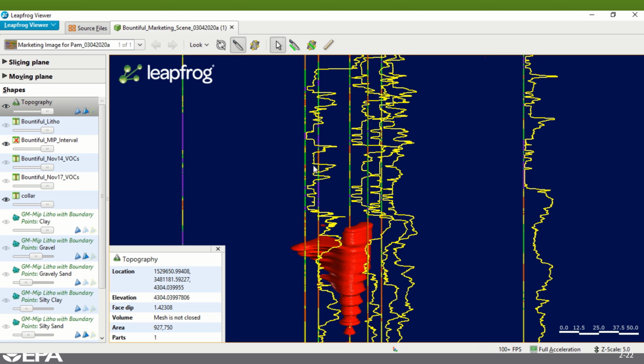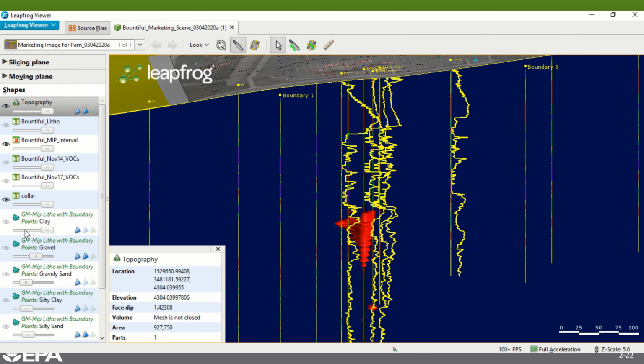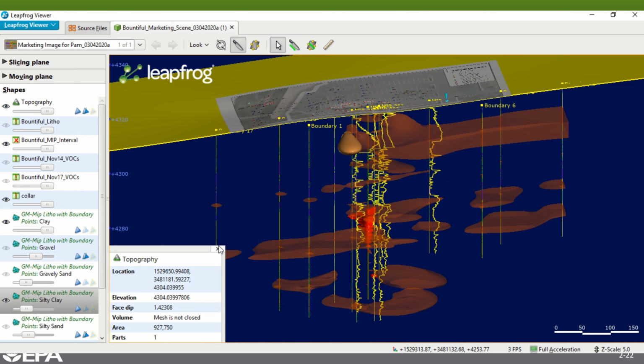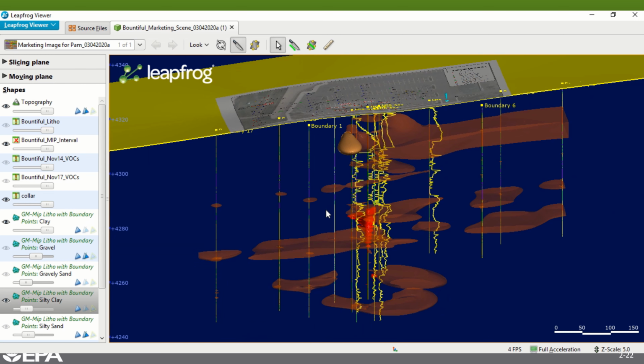But you also get the electrical conductivity response, and you can see these big kickouts from individual boring logs, and those kickouts can then help us interpret or interpolate some of the geology. So let's go ahead and turn on a couple of the key geologic points now and look at the interpolation of those. So we can turn on the clay, and there's not a whole lot of clay at the site. Really the unit that tends to be driving the location of the contaminant mass seems to be the low permeability clay units located here.